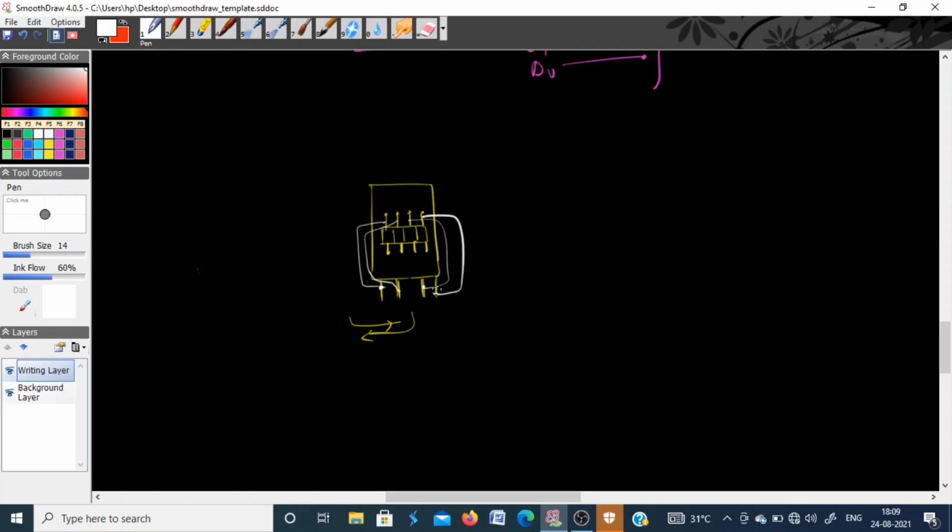Whenever it is a write operation, the data will come from the databus, go on the input lines, and when you assert the control signal write, it will be placed in the flip-flops. If it is a memory read operation, the data will come through the same 4 lines, so these 4 lines must also be connected to the databus.